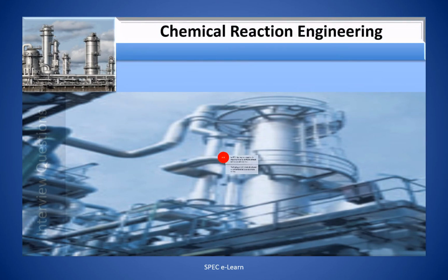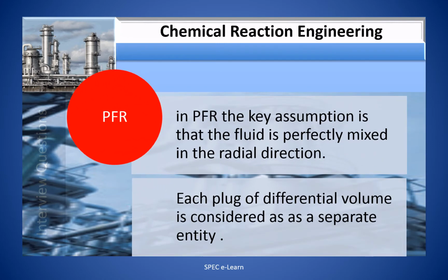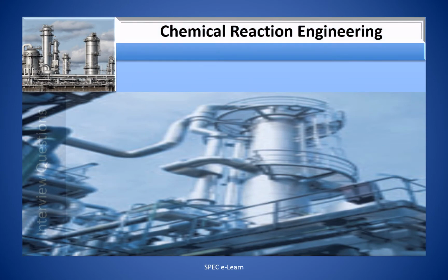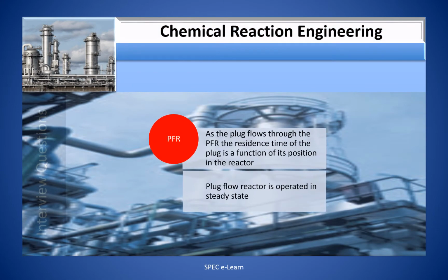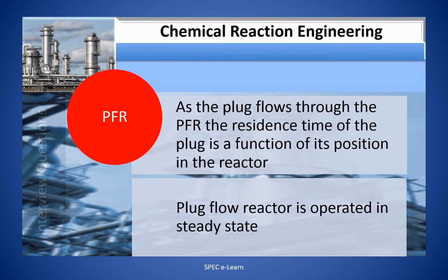In a PFR, the key assumption is the fluid is perfectly mixed in the radial direction. Each plug of differential volume is considered as a separate entity. As the plug flows through the PFR, the residence time of the plug is a function of its position in the reactor. Plug flow reactor is operated in a steady state.